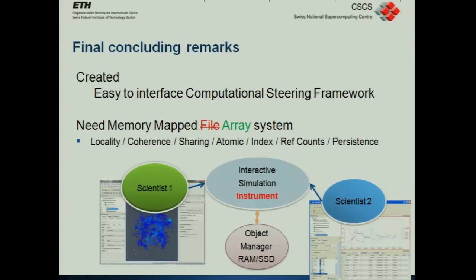So we've leveraged ParaView again, which has a rather nifty facility, which is when you write a filter in ParaView, it says, I want to take all this, I want to do something to it, and then you have 3 parameters. You can specify a little bit of XML, and ParaView parses that and generates little GUI controls. And we've extended that very slightly to allow us to create steering controls where the engineers write some XML, which basically says, you're allowed to modify this, you're allowed to modify this, you're allowed to modify this. This is a 3-component XYZ vector. This one is just a simple scalar. And we also allow you to write meshes into us with this name and in this location and with this certain criteria.